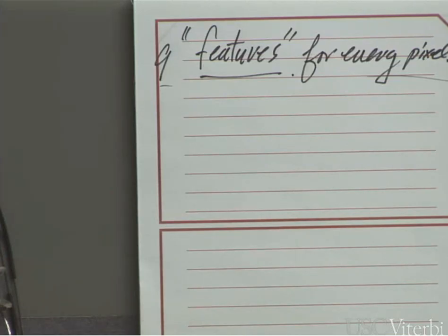I think one problem with Lowe is that he didn't take the 483. He didn't take DSP. If he had taken the DSP, the first several lectures, he immediately find the frequency response of these 3 filters, and immediately understand there are 3 filters. One is a low pass filter, one is a band pass filter, one is a high pass filter. So these 3 implement exactly low pass, band pass, and high pass filter. That's it. So you divided the frequency in 3 bands, Y and X. So totally you divide the whole spectrum into 9 bands, X3 low, middle, high, Y low, middle, high. In total you have 9 filter bands. That's it. Nothing more than that.